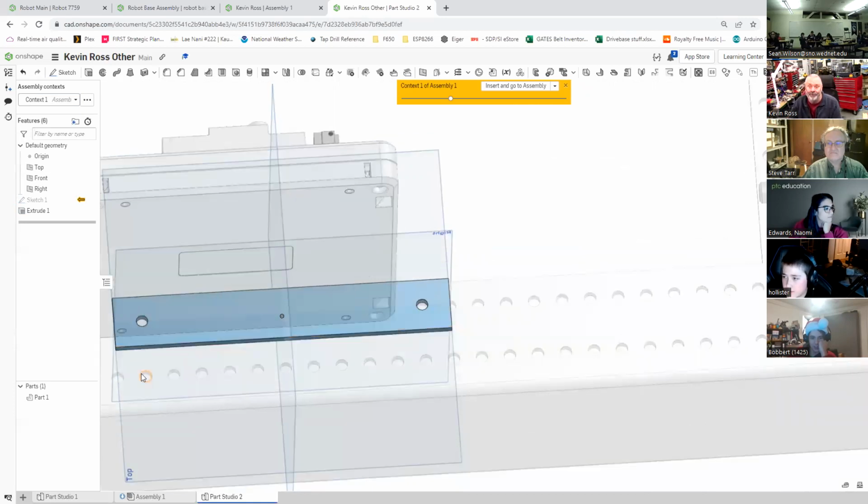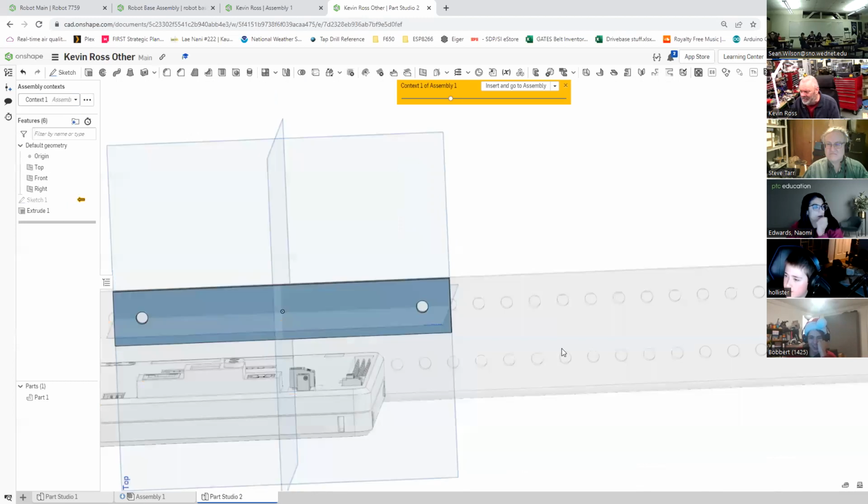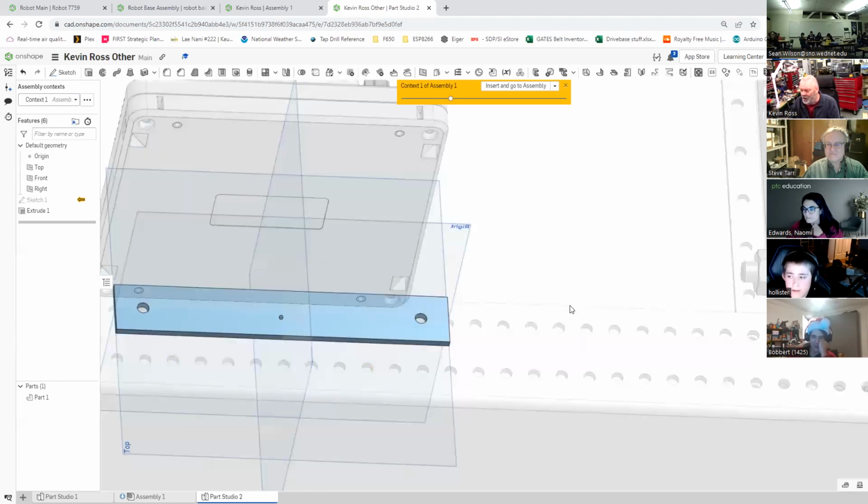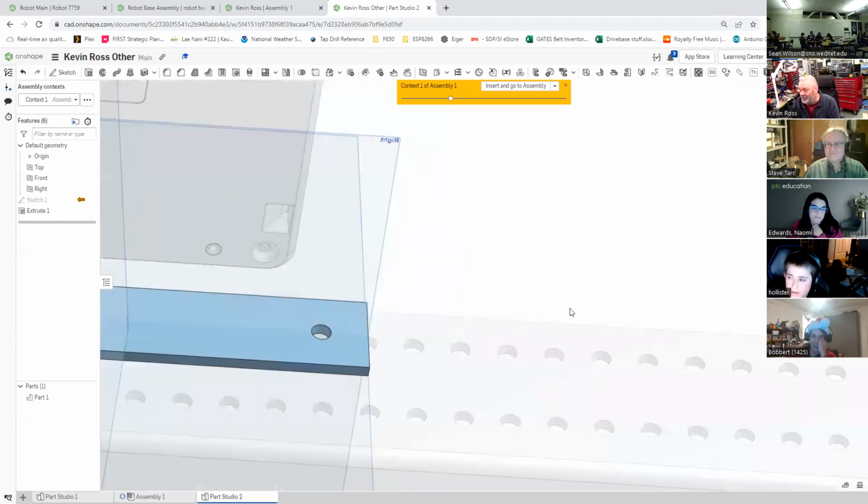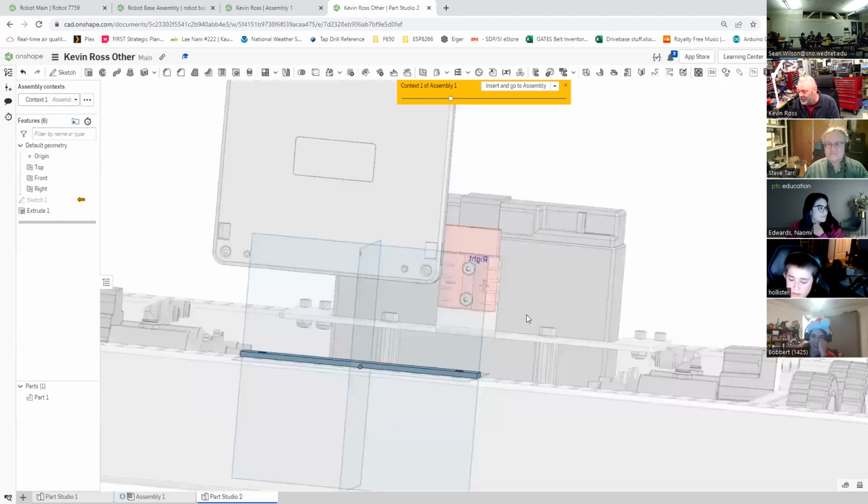Notice I didn't have to dimension those holes. I projected them, so they're kind of fixed in space. If the model underneath changes, since I did use the 6-inch dimension, that's okay. But the rest of it is all referencing the context of this part. Does that make sense? How am I doing? Make sense? All right. And now I need, well, turns out I can cheat and I can grab some measurements.